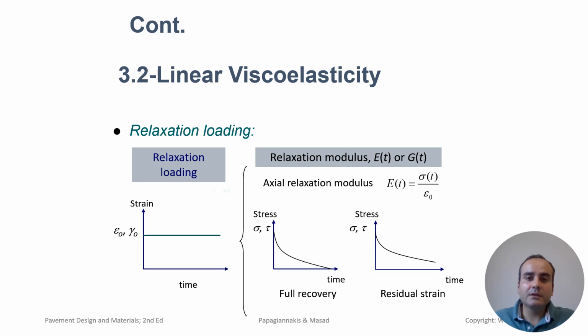During cooling, the pavement contracts, potentially creating tensile stresses. If the asphalt binder has good stress relaxation properties, it can gradually release these tensile stresses over time, reducing the likelihood of thermal cracking. This is particularly important in cold climates where asphalt is more prone to brittle failure.